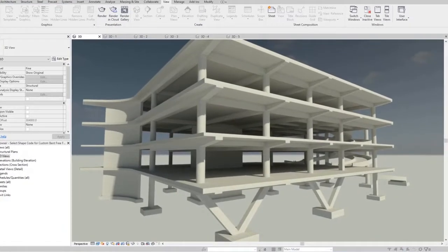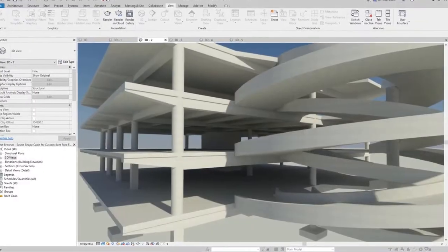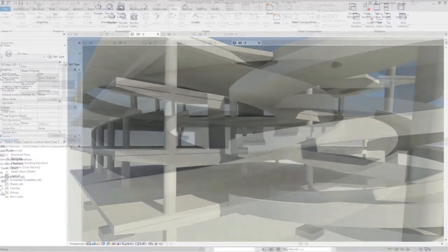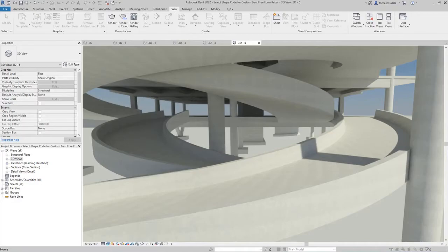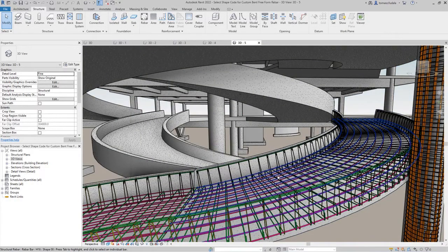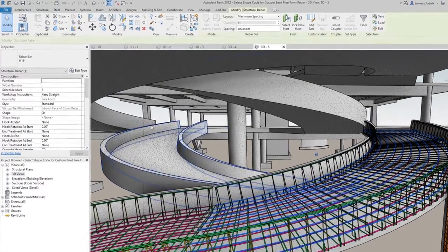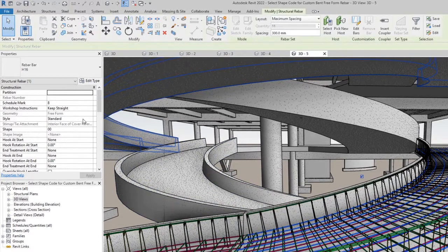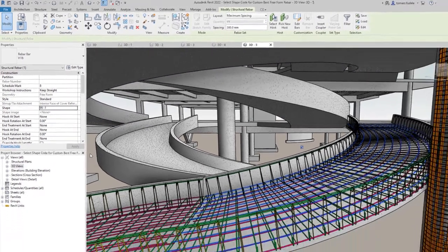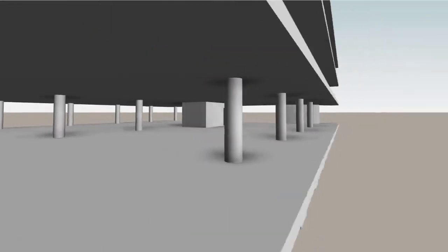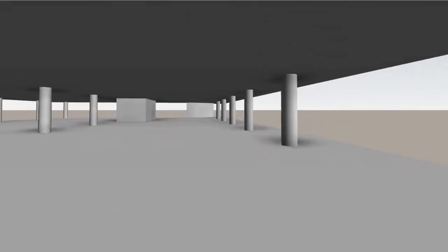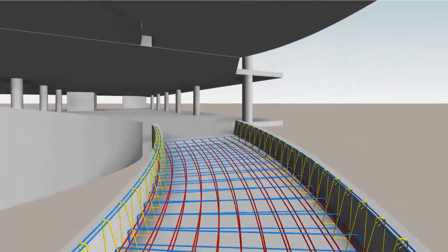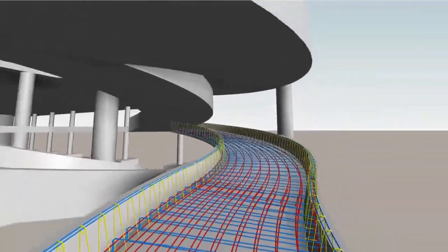In Revit 2022, rebar detailers can assign shape codes to custom bent freeform bars, enabling you to provide better fabrication instructions. For example, you can now distinguish between bars to be bent outside versus the shop. You can manually assign the desired shape code to bars per their local fabrication conventions or the code of any shape loaded in the project. This new functionality enables you to provide more complete bending instructions, leading to more accurate rebar bending schedules for fabrication.